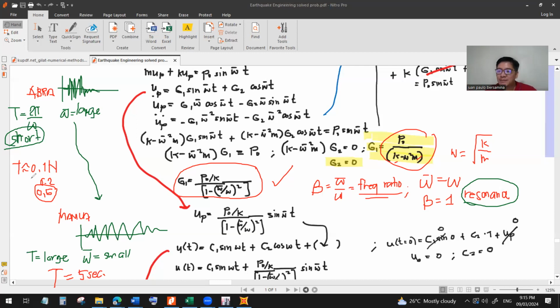Proper construction is a different matter. Although your structures are short period, if they are properly constructed and you follow the seismic detailing of the code, there could be damage, but not collapse. Okay, but anyway, damage. So the idea is, with this kind of resonance, the seismic wave will resonate with the short period structure, therefore they will have damage.